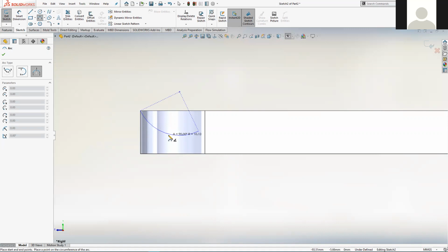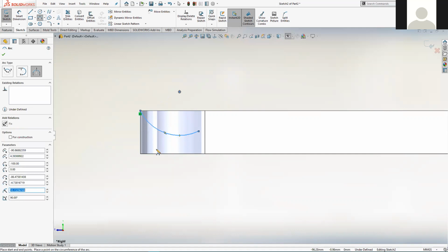They're just for my reference as the user. It's telling me that when I get to that point, my arc has gone through a quarter of a circle. So it's saying there on the readout, 90 degrees. So it's just indicating that that's a special arc. It's swung through 90 degrees. As it happens, that's around about what I need. It isn't exactly what I need, but I'll probably click when that appears like that.